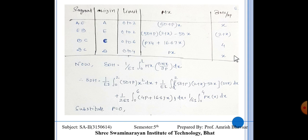When we collect this data, the mathematical steps follow. So simply what we have to do now: delta DH is equal to 1 upon EI integration 0 to L of Mx into del Mx upon del P into dx.